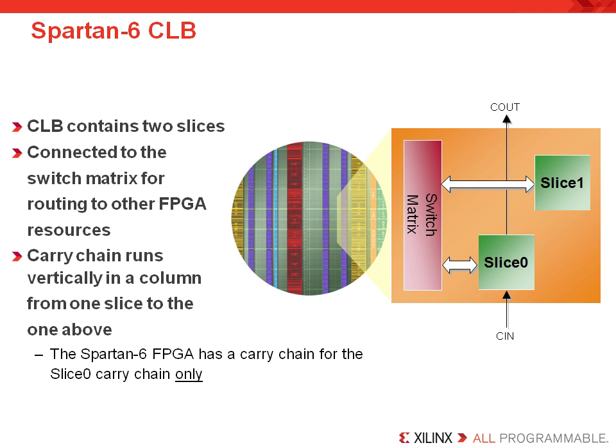Besides LUTs and registers, slices also have carry logic resources, which are designed to implement arithmetic logic functions with high-speed performance due to their dedicated carry chain, which runs vertically in columns from one slice to another. Spartan-6 is designed so that it only has one carry chain per CLB, and it is associated with the slices in column 0 of each CLB.